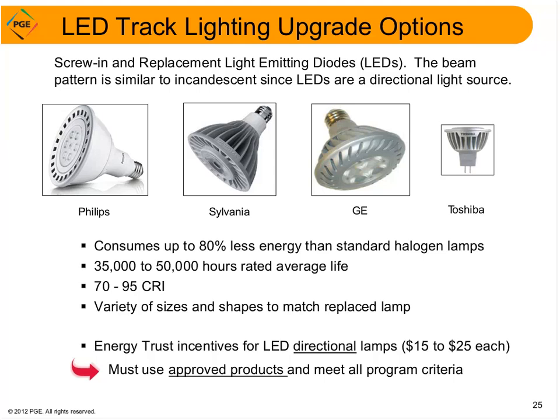And there are many varieties, including the PAR 38s you see here, as well as MR16s. The energy savings and excellent color quality make them a compelling choice. And maintenance savings is another huge advantage. Because these can last 35 to 50,000 hours, it's going to be less expensive, let's say, to buy one LED lamp that lasts 35,000 hours or more instead of 10 halogens over time.